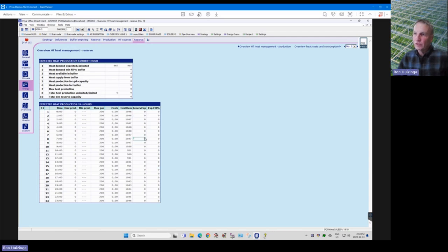So what's going to happen is you're going to fill your tank during the day for CO2. Then it's going to be full enough. It thinks it needs roughly, say, maybe 60 to 70% all night long in that tank because of my heat demand in the greenhouse. But I filled up my tank now for up to say 80%, 90% of heat. So then the boiler won't run all night long.